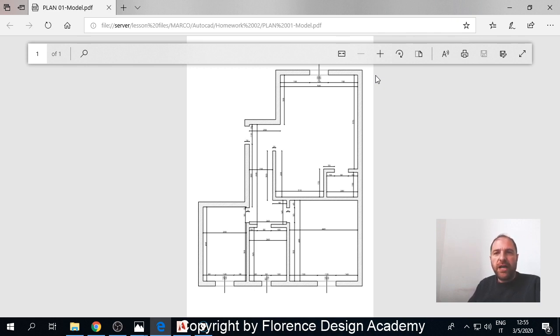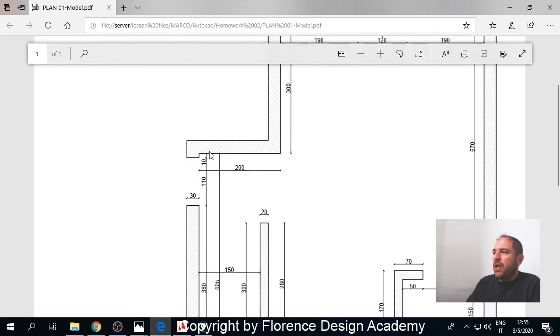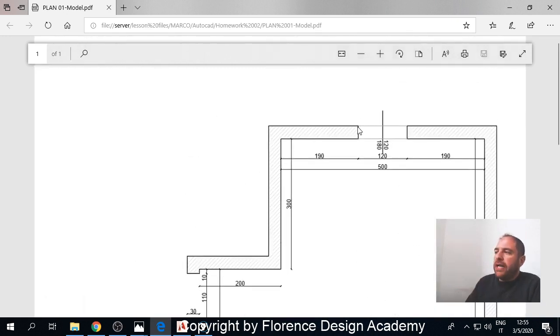Mindful Music Incorporated says, do you have preferred line weights for walls, windows for this homework? Not that I have, but in general, you need to follow a very simple rule: your line weights should always be divided by 2 when you go from thicker to thinner. What does it mean? Let's say you make these 0.8.